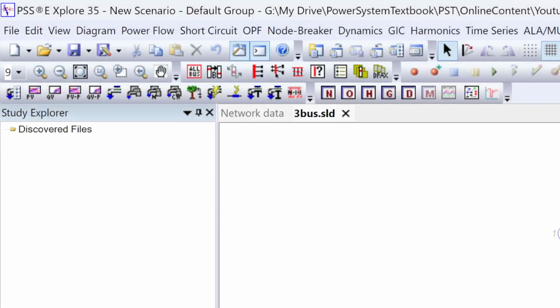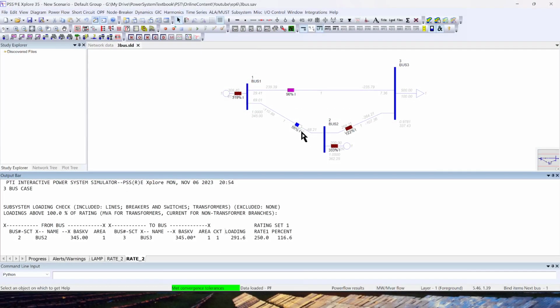And then this line is 55%. And then this is the transmission line which is overloaded, 122%. Now you may be wondering that here it says the percentage overload 116% and here it's 122%. That's because there are two types of overloading percentage to compare. It's either based on current or based on actual MVA itself.